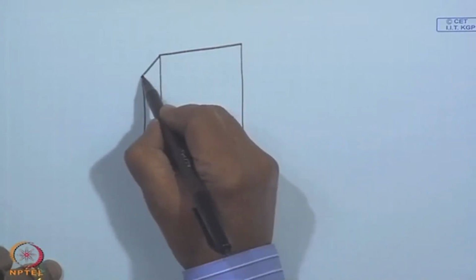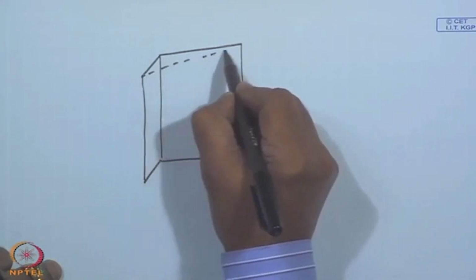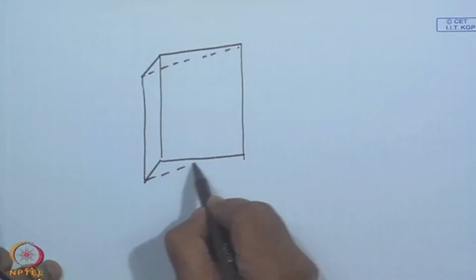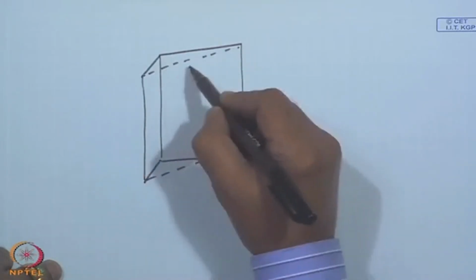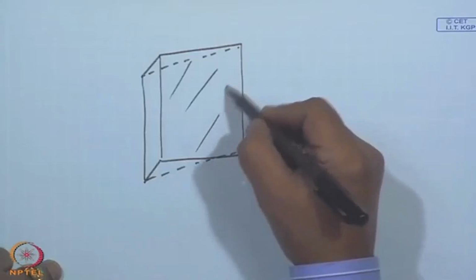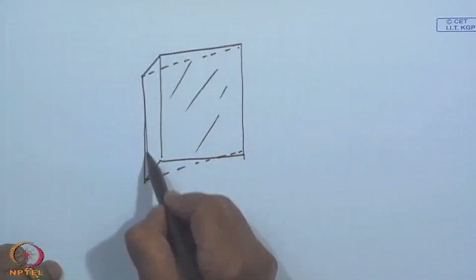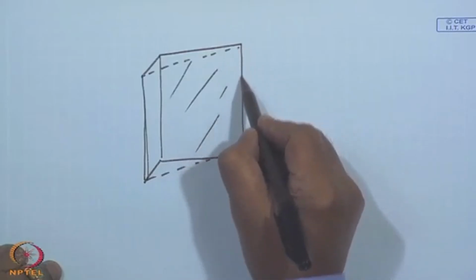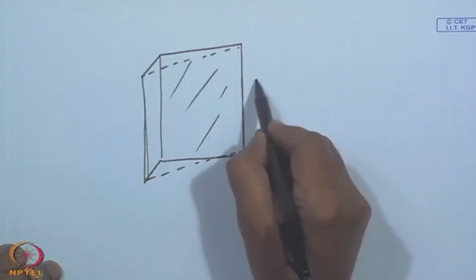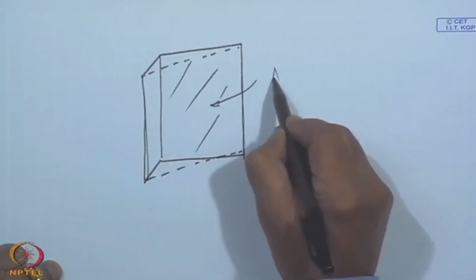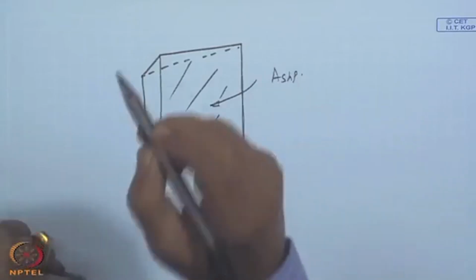So, from here, this will be your shading plane, the one that joins the edge of the wing wall to the base on the other side of the wall. So, this is the shading plane for the wing wall.